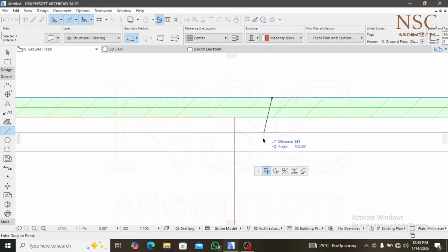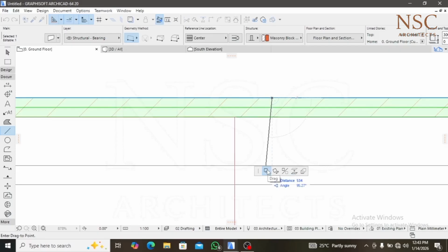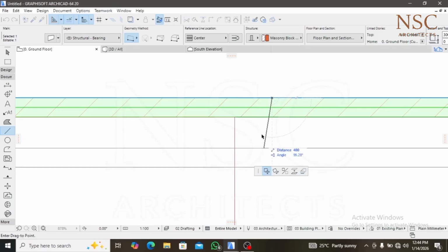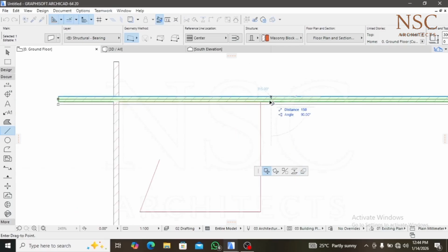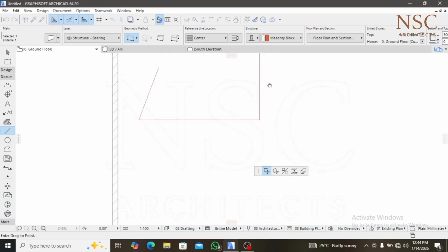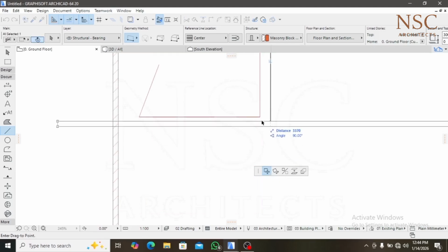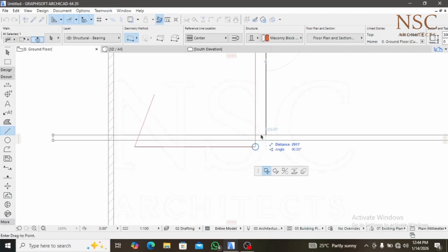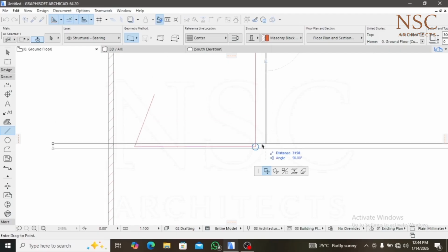So now your aim is just to drag this wall. To drag this wall, you click it and make sure that it's on drag, then you come down. Remember to hold your shift just to get your accurate line. Then to duplicate it, you click control as you are dragging it. You see it's now showing plus line. Let's unclick it. The plus line has gone off. Let me click it again. It's showing again. So you drop it there.